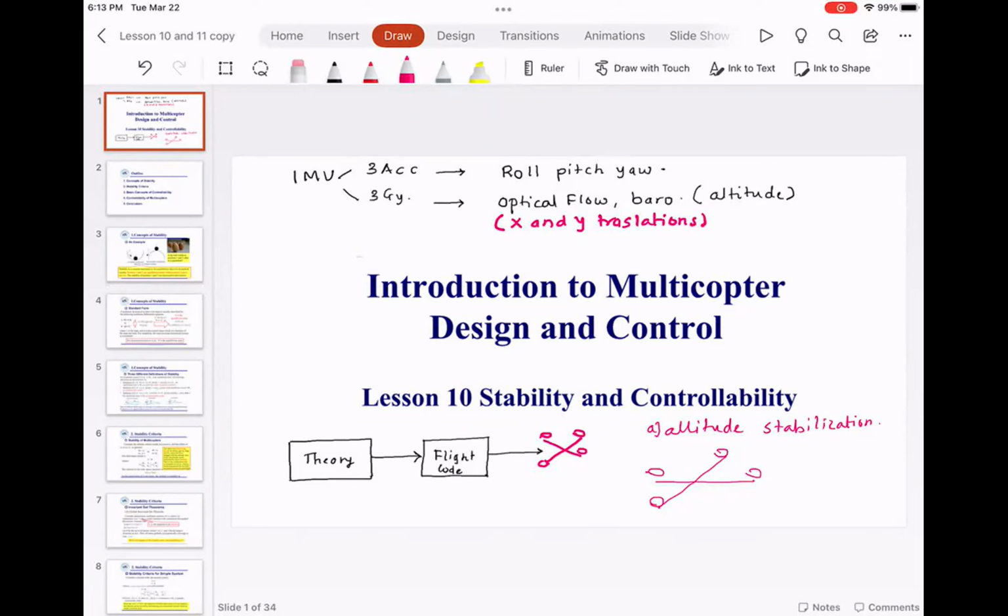And then we would tune the gains so that the Mambo is stabilizing itself as a pendulum. And once you have robust performance, which means you have tuned your gains very well, then you can take that string off and have the props fly at full speed, and you will see that your Mambo will hover